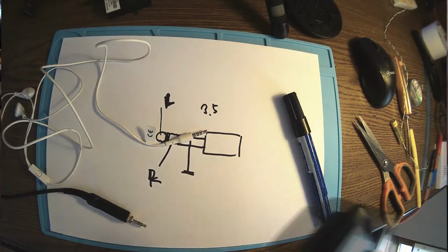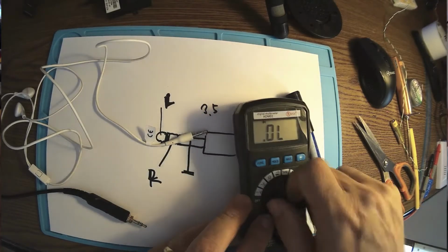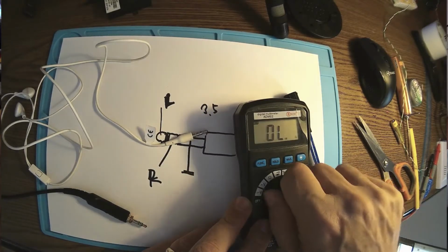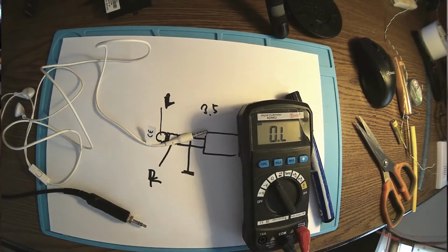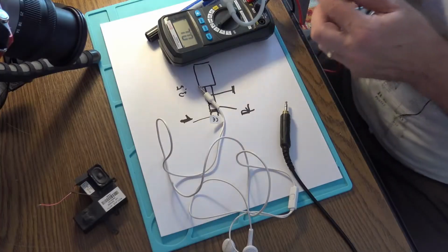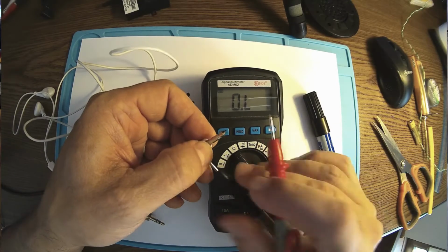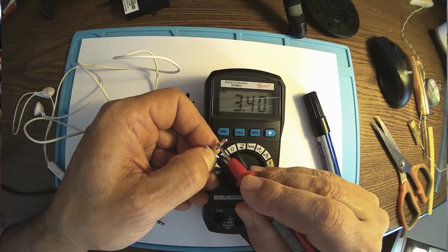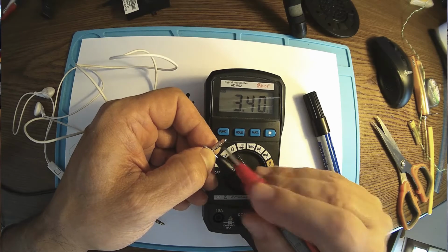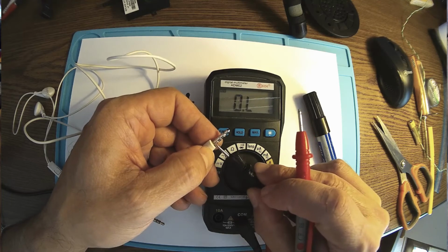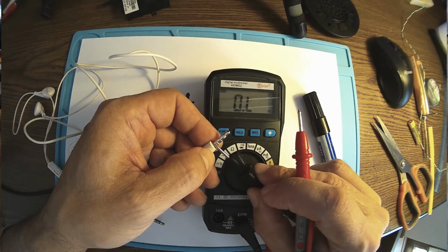If you have a multimeter, that will make things very, very easy, because you just go to ohm meter, like I'm doing now here. We get the inside ring, let's call it inside, and we have the right can, the right headphone, and the left one. So probably this is not the ground in our case. Sometimes the ground is here, the third ring.